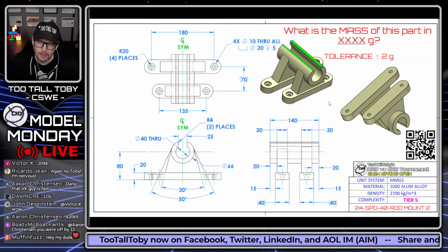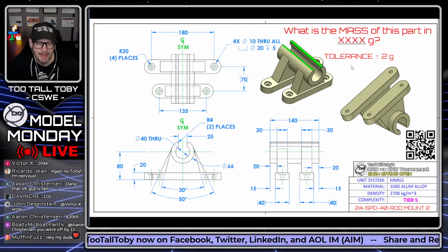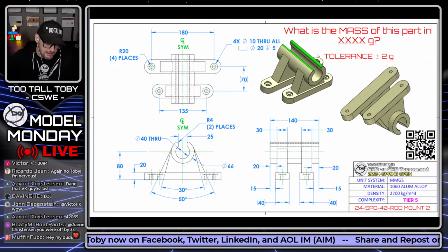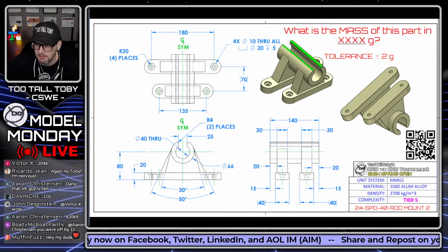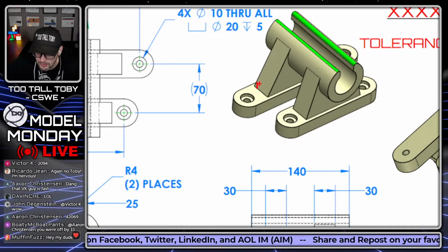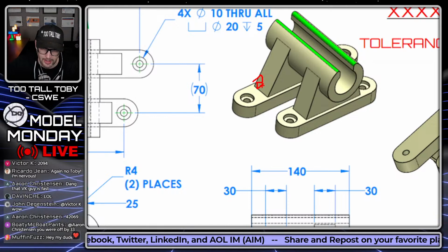So whenever we're creating geometry in 3D CAD, I lately have been using the term discretize. This is a term that you get from mesh modeling when you're doing finite element analysis. You take the entire model and you discretize the model into tetrahedral elements or into hexahedral elements or brick elements. But if you're doing tetrahedral elements, they would be kind of triangular shape.